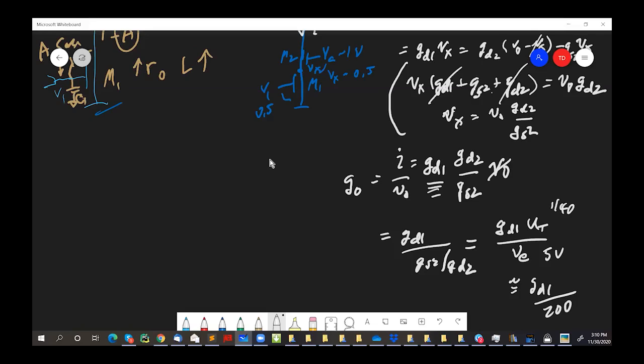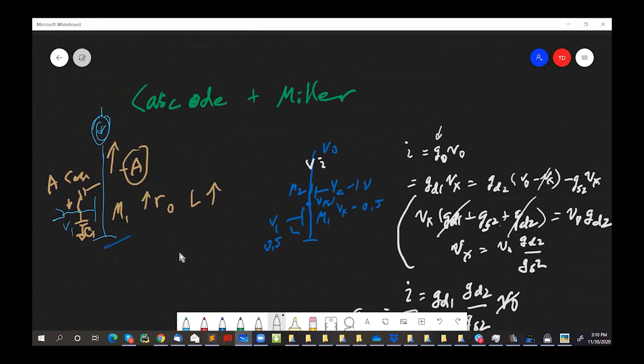So that's a nice trick. Anytime you want a high voltage gain stage, you put in a cascode like that. That'll get rid of the Miller cap and it'll increase the output resistance a lot. Generally, it takes away a little bit of headroom, right? Because now this gate here has to be adjusted to hold the drain of the M1 transistor just in saturation. So you need some independent thing that will generate that cascode voltage for you. You have to hold the drain in saturation like a couple hundred millivolts or so. And it takes away a little bit of headroom.